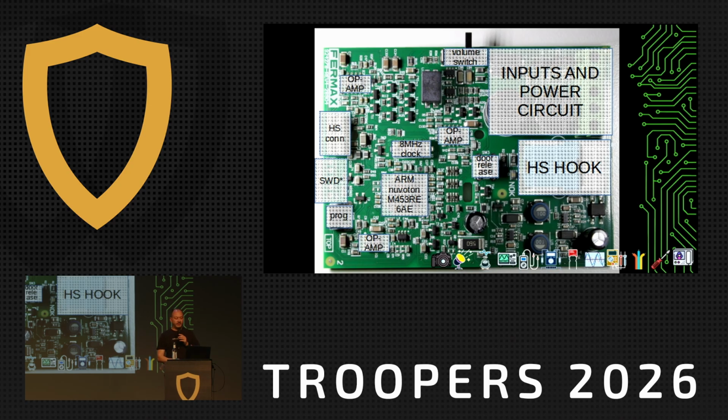It's serial wire debug. And one important thing about it is you can see that someone had soldered there before. So that means at the factory, as part of testing or programming every single device, they are actually soldering a connector on there. Which means there is a slight chance that it's still electrically connected, and maybe the microcontroller isn't locked. So we can try to use that.